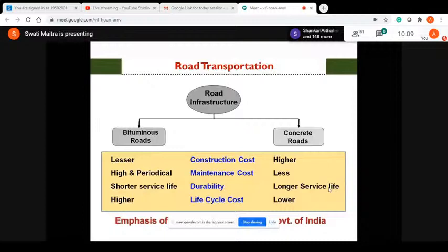But not all are very popular. In India, we particularly have jointed plain concrete pavement in most of our highways. JRCP or jointed reinforced concrete pavements are much less common, even in the US. In India, it is not there. CRCP is also not constructed in any major project in India, though in the US, several highways are constructed with this.